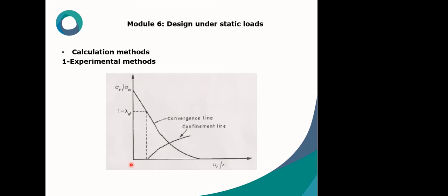Generally, this method is based on the relative displacement of the opposite points on the tunnel wall. Following the convergence of the tunnel section provides the possibility of controlling the appropriate retaining and forecasting the required reinforcement if necessary.